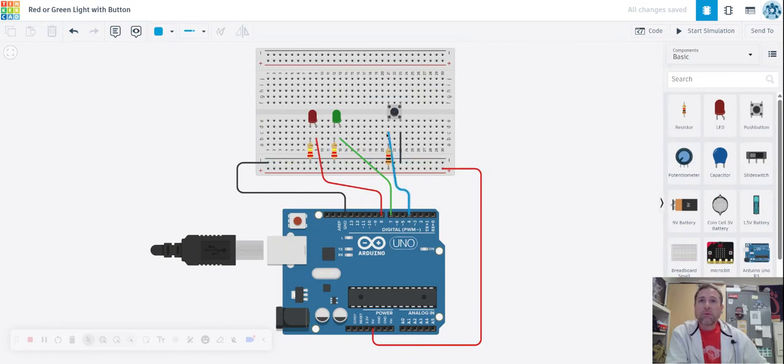The microcomputer will read through this blue wire that the button has been pressed, and then once that button has been pressed, it will randomly tell, like I said just a minute ago, one of these two pins to be activated and send power to one of these two LEDs, and either of these will light up. So at this point in time, we have completed our entire circuit.